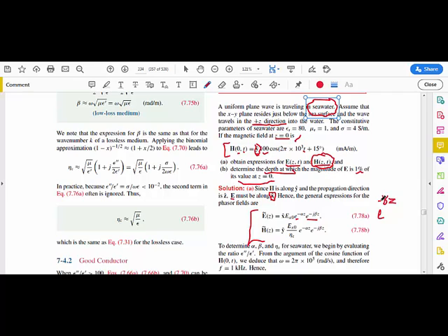We just decompose this gamma, or the propagation constant, into these two exponential functions, but please note the first exponential function is real and it's responsible for the attenuation and its effect on the magnitude, just on the magnitude. And the second one is an imaginary exponential responsible for the phase and the sinusoidal. This exponential gives us the sinusoidal.